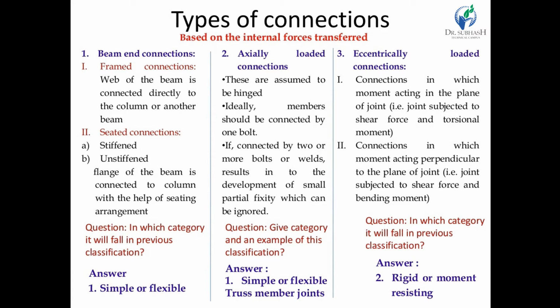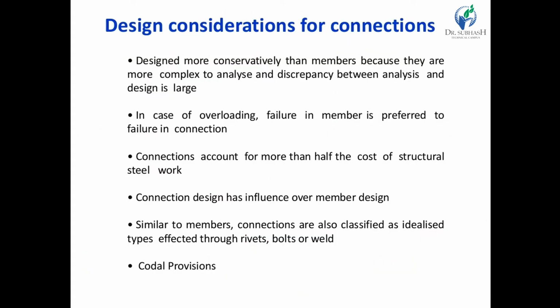Now eccentric loaded connection. This is a connection in which moment acts in the plane of the joint, for example a joint subjected to shear force and torsional moment. There is also a connection in which moment acts perpendicular to the plane of the joint, for example a joint subjected to shear force and bending moment. These can be classified as rigid and moment resisting connections. So as per internal force transfer, there are the subcategories: simple connection, simple or flexible truss joint, and rigid moment connection.